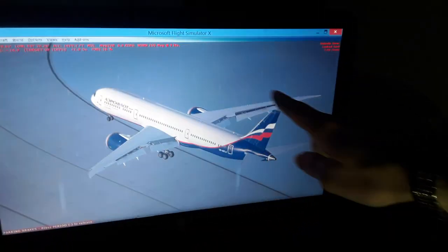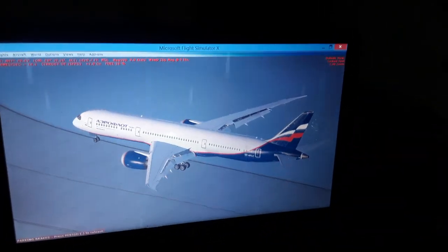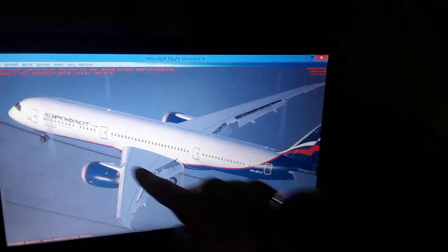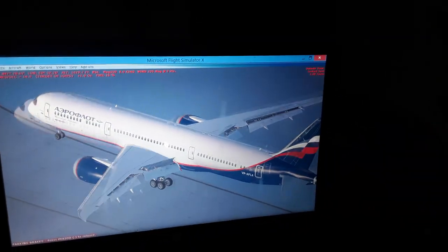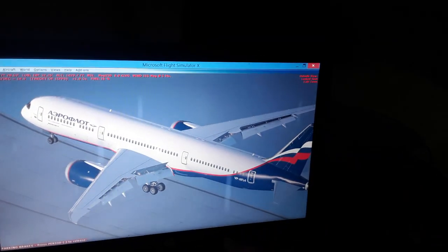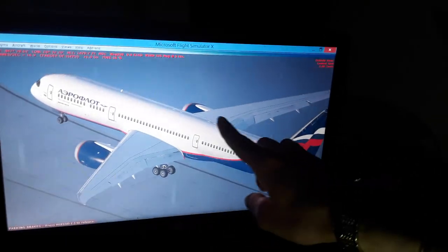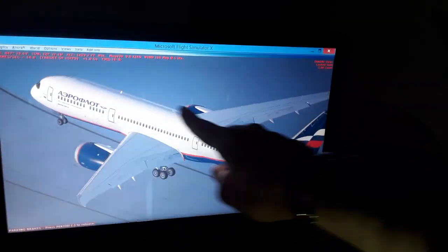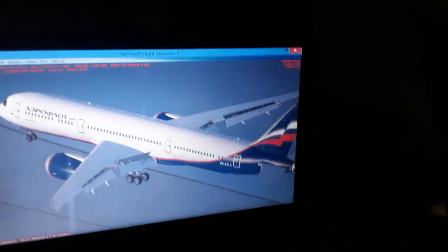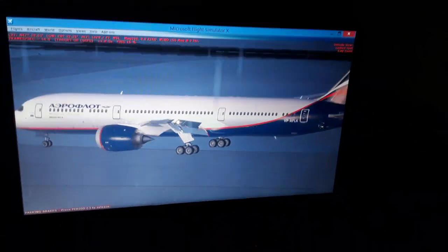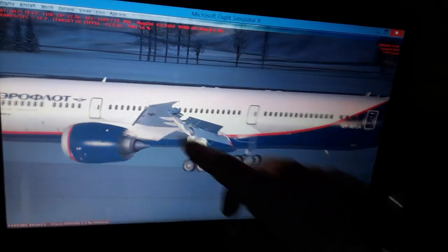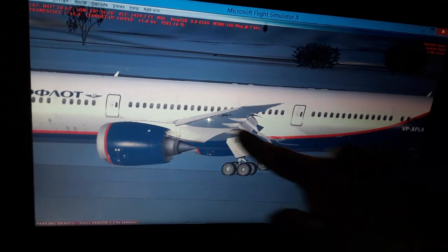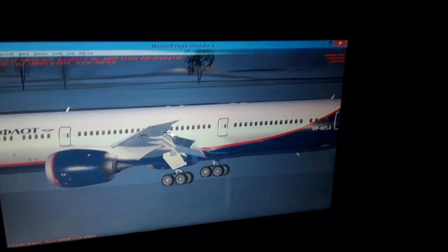So you can see the surface area of the wings when the aircraft will be flying later. We have the aerodynamic flow. When we fly fast, moving fast the aircraft, it will give us aerodynamic lift. Over here it acts where the center of pressure is, pretty much close to the engine, so we will act over the weight. It will make the aircraft fly up into the air. So below the wings, you can see it's more flat. So generally using Bernoulli's theory of fluids, the airflow is moving slower, so we have higher pressure, which will push the aircraft wings up into the air.